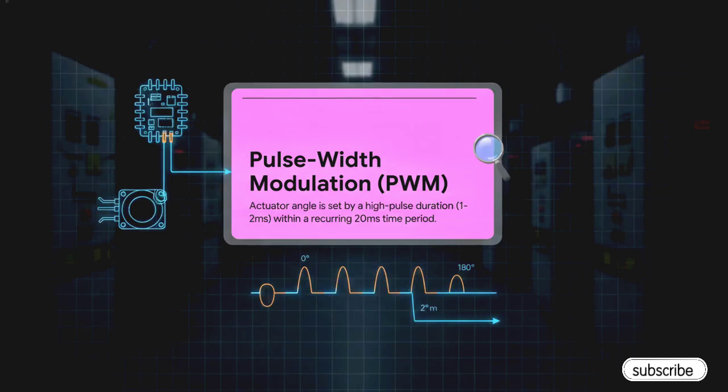Well, we do it through something called pulse width modulation, or PWM. With a servo, the position isn't determined by how much voltage you give it. No, it's all about the duration of a high voltage pulse. For example, a 1 millisecond pulse tells it to go to 0 degrees. A 2 millisecond pulse tells it to go to 180 degrees. And this all happens inside a repeating 20 millisecond cycle. This is, for all intents and purposes, the standard language of servo control.